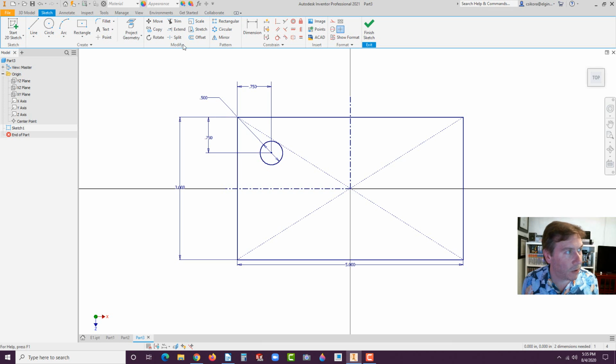Click. First of all, just go to the mirror tool icon right up here, mirror. Now notice this, there's a select button and a mirror line. Now notice the select is blue. It's been pushed in already for us. So that's what you want to mirror. So click on the outside of the circle because that's what we want to mirror. Now go back here, and this is for selected mirror line. Notice it's singular, it's not plural, so you can't do both sides at once, at least as far as I know.